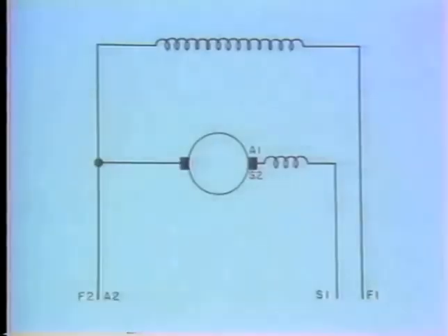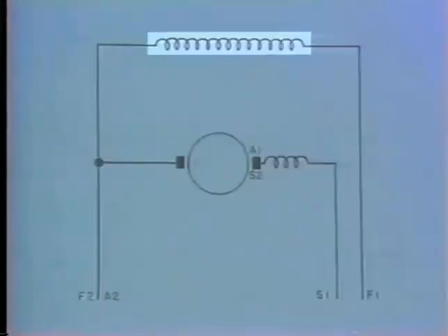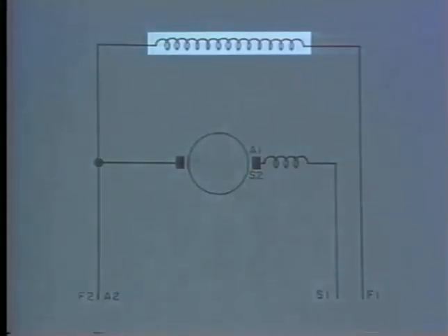You'd use an ohm meter, and you'd check each circuit individually from end to end. And that's exactly what we're going to do. Here's the diagram. As you can see, there are two paths for current flow. We have to break them up in order to check the circuits one by one. Lifting the brushes off the commutator gives us 3 individual circuits again. This time, we'll do the shunt field first.